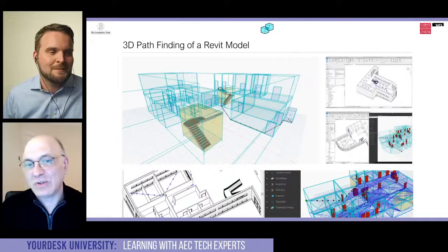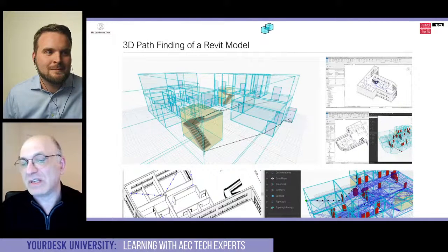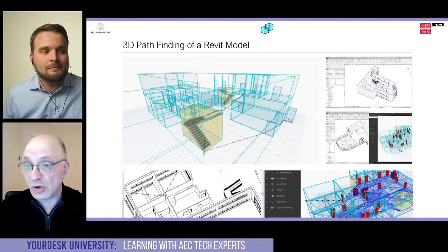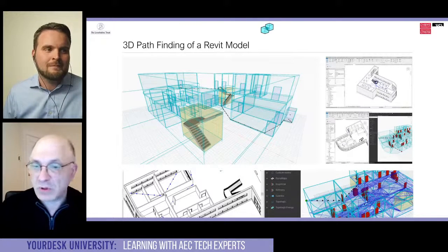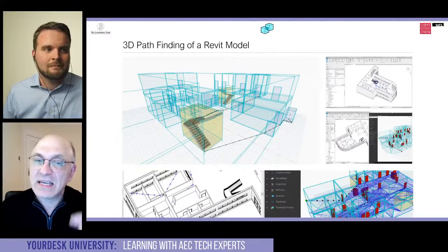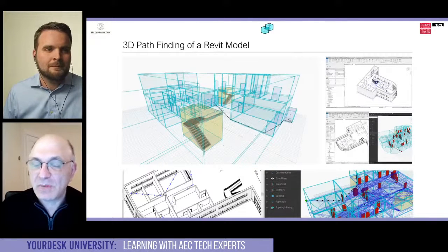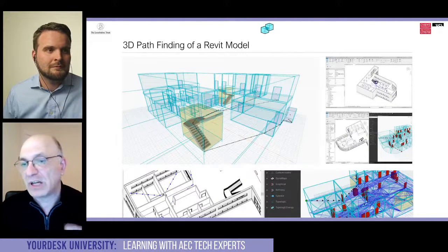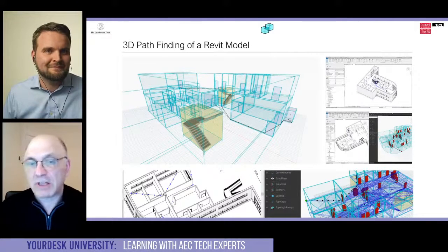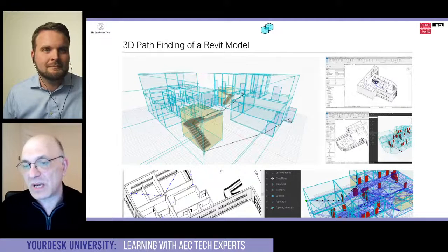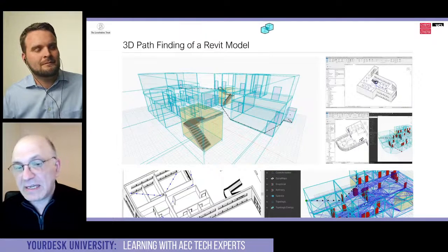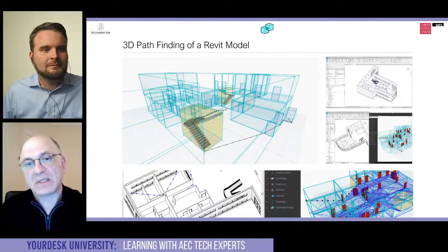One thing I used for sure here is that the doors in Revit, you can check a box and you can ask the doors to store in them which two rooms they connect. Obviously a lot of people do that and they need that information. I would assume a door should always know what rooms they connect. I mean, that should be the default. But I found out, and I'm not a Revit expert, I found out to turn that on in order to get the information out of the doors. But the visibility graph that you see in the lower right corner is really what is important here.